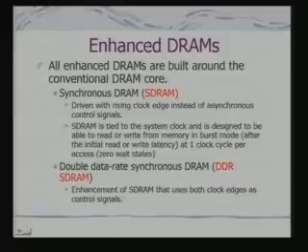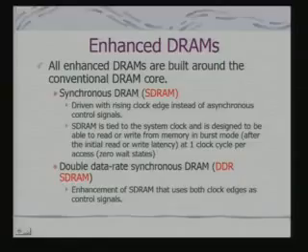Now, variations of these to speed up the DRAM access have been suggested, which is synchronous DRAM, or SDRAM. In fact, in many of the PCs today, when you buy memories, you buy SDRAM. The RAM control signal is based on the rising clock edge instead of asynchronous control signals, that is RAS and CAS. So SDRAM is tied to the system clock or the bus clock and is designed to read or write from memory in burst mode after the initial read or write latency, at one clock cycle per access.